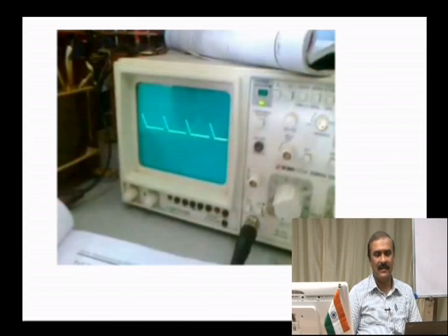So, in this class, in the resistance firing circuit, as you have seen in the graphs depicting the firing angle, alpha is restricted to 90 degrees. And you know why it is exactly at 90 degrees. With respect to the R circuit, the firing angle alpha has a restriction, exactly at 90 degrees.